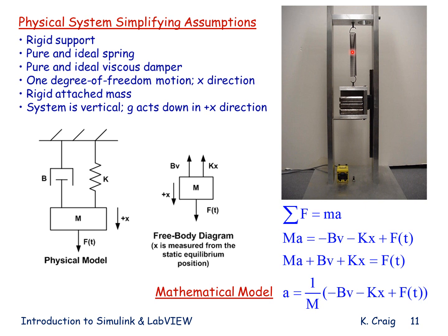Neglecting the mass of the spring is appropriate if the mass of the spring is much, much smaller than the mass attached to it. This is acceptable except in very high-speed applications. The motion of the spring will dissipate energy, but what I'll assume is that energy dissipation is negligible compared to other dissipation mechanisms, notably the linear bearing, which is the source of almost all of my energy dissipation.